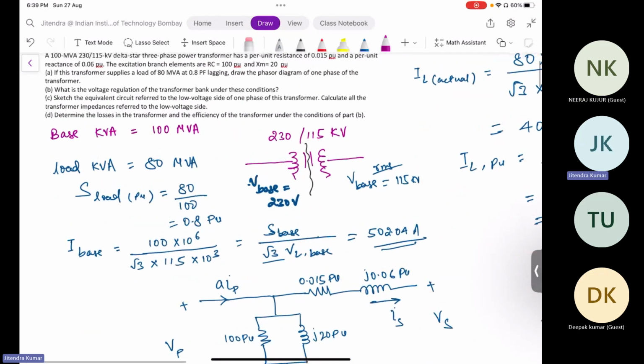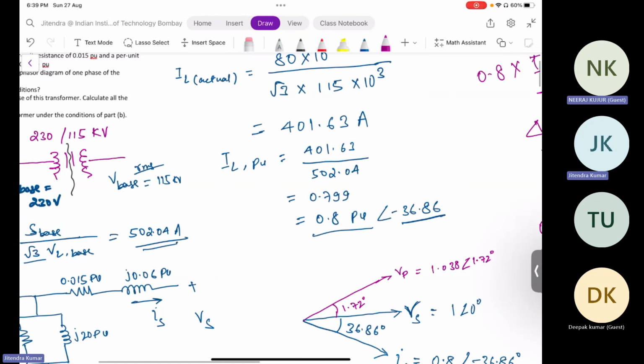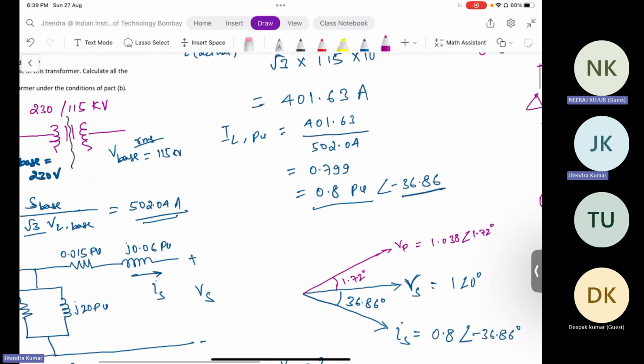Could you please lead me on how to proceed with the second part? Sir, one thing came to my mind. For drawing the phasor diagram, we can assume primary or secondary, any voltage, at 0 degree, according to our convenience. Yes, it's in your hand, according to your convenience. It will be more convenient when you consider the side whose parameters are already provided, because you know that value. You know only the unknown value, so the known value should always be taken as a reference.